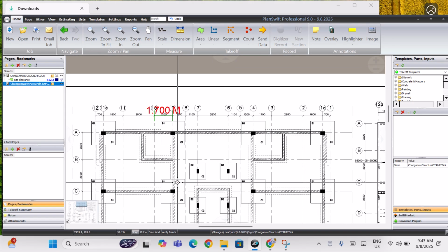And now we can find out the length of the foundation walling, which is drawn all over the building. So you come here. Well, I like to measure walling using the linear millimeter, which is basically the perimeter. Then when you're quantifying, you can multiply by whatever custom height comes up either on site or in the specification you're given. So for foundation walling, you come to the linear on the dialog box,